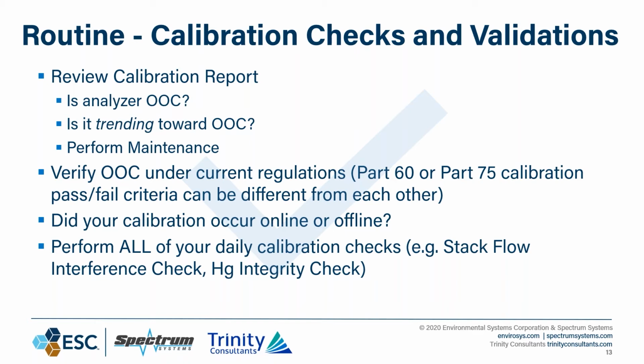And we've talked about this in the past. Most vendors recognize that once your bottle pressure gets below 150 PSI, they will tell you, we don't consider our bottles reliable below 150 PSI. I know a few of them that will tell you to be extremely wary at 200. So going into a weekend, if you're getting ready to go off on a 4-day and it's Friday, it's a good mid-morning check to do, just for peace of mind. You do not want to get a call out at 2 o'clock in the morning because of an empty bottle. That's just wrong.